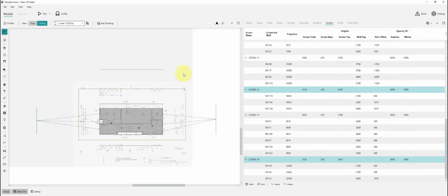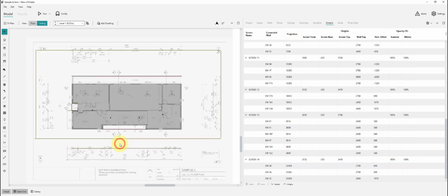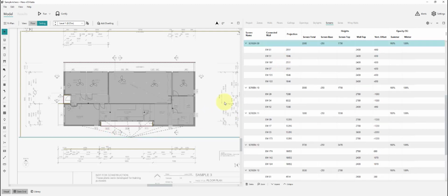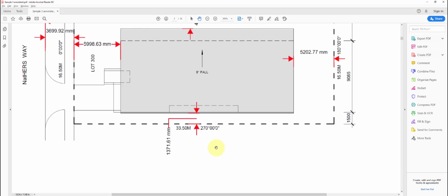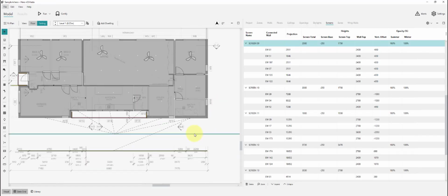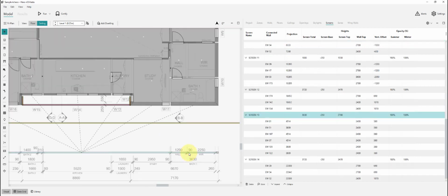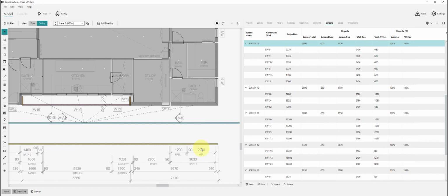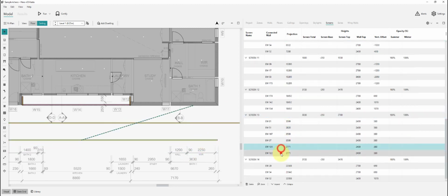And we need to just make sure we've got their positions relatively good. So clicking this screen here, we can see its projection, or its lowest projection, is 1850 off these south walls, and in the site plan we see actually that dimension is more like 1400 or 1370, so we're just going to want to shift that back until we're closer to that kind of mark. And then this southern building here will just be twice that, so if we were targeting 1400, we'll target this one at 2800 on its lowest projection out from adjacent walls.